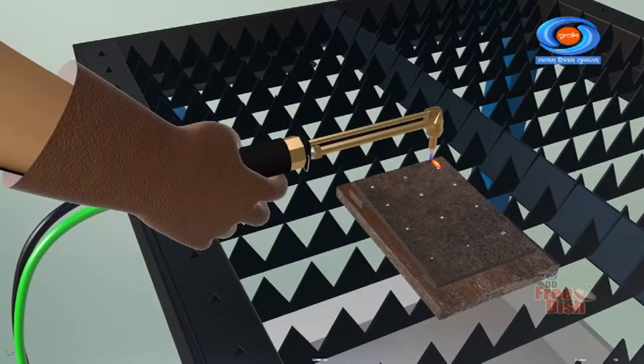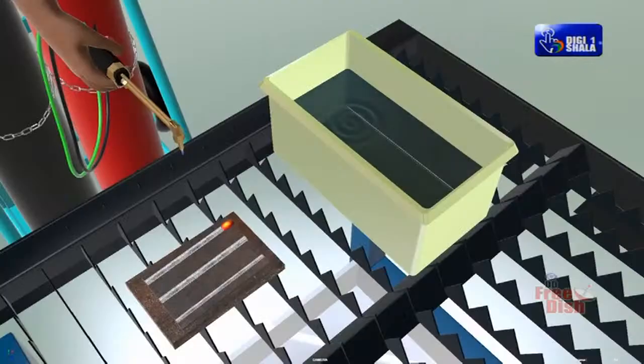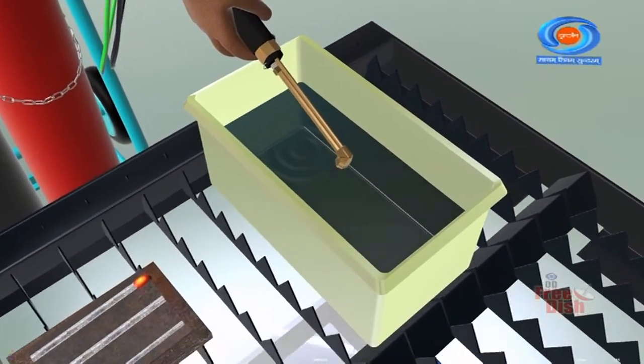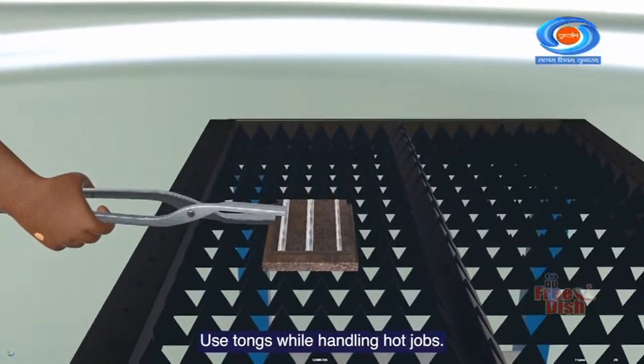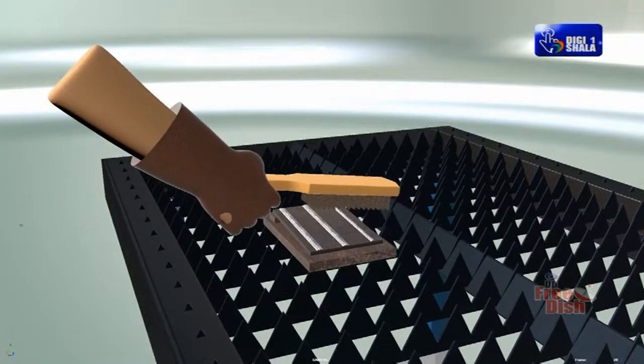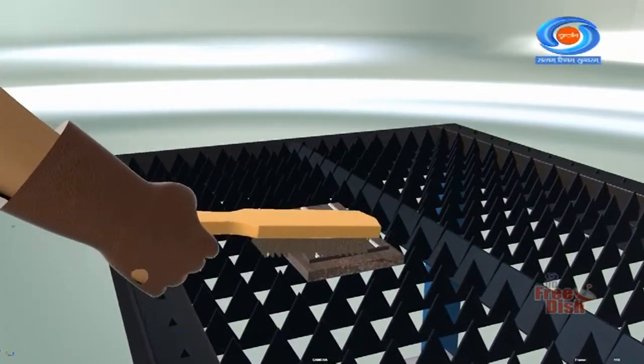Quickly lift the blowpipe at the left end. Extinguish the flame and cool the blowpipe in water. Use tongs while handling hot jobs. Clean the fused surface with a steel wire brush.